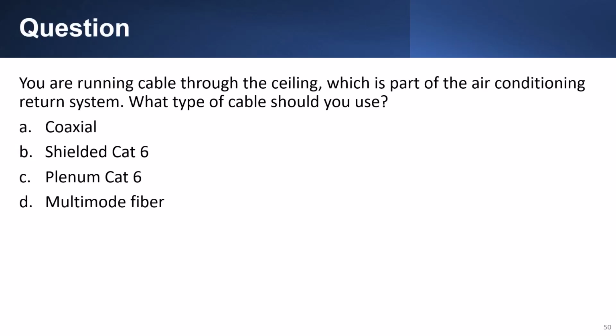Question: You're running cable through the ceiling, which is part of the air conditioning return system. What type of cable should you use? Answer: Plenum Cat6.